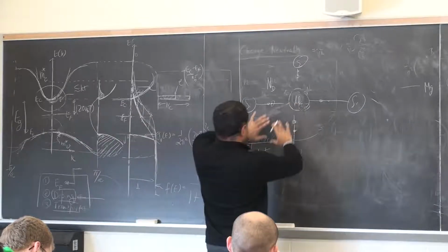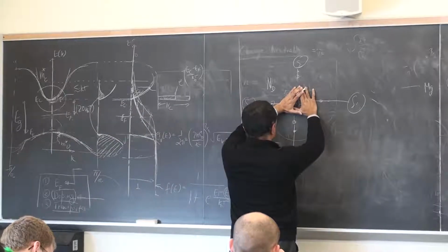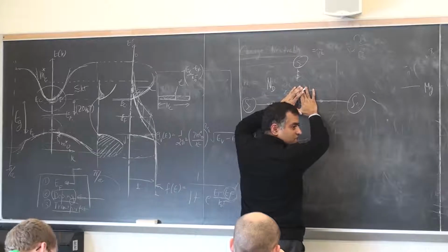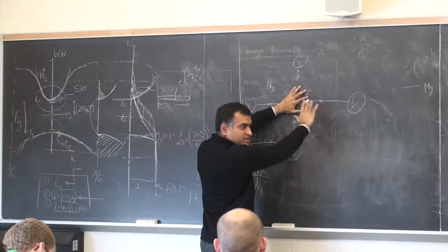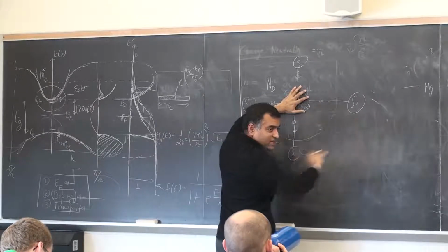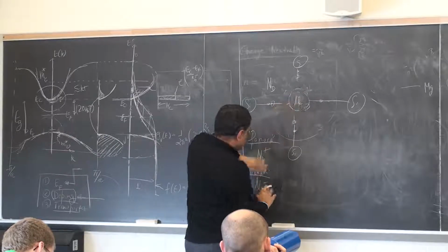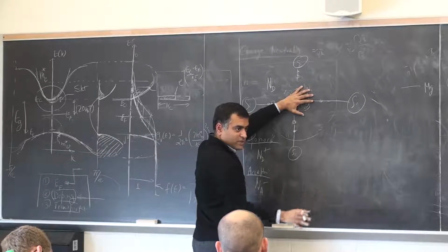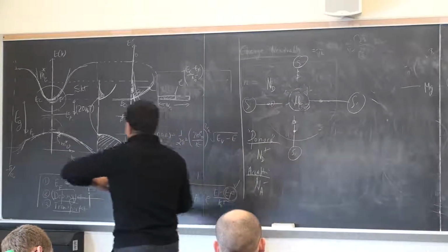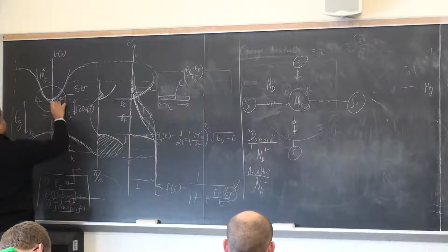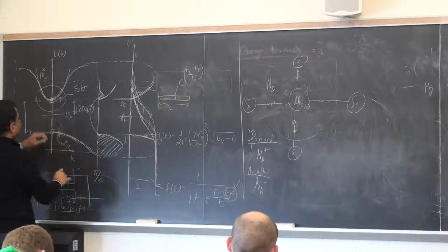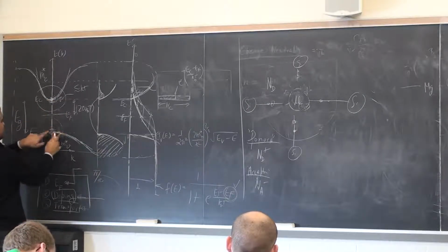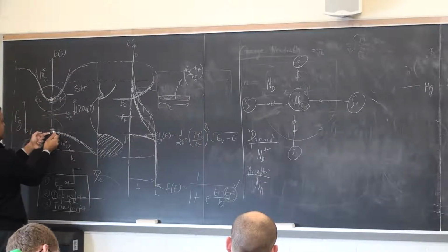It gets negatively charged, the acceptor. And the ND plus ion cannot move in the crystal. It's stuck in the crystal. It's immobile. What is mobile is the electron that came with it. Similarly, the acceptor ion is immobile. What's mobile is the hole that came with it. So the hole is an empty state here, and the electron is a filled state here. And these came from the acceptors, because the acceptor state pulled up an electron here.